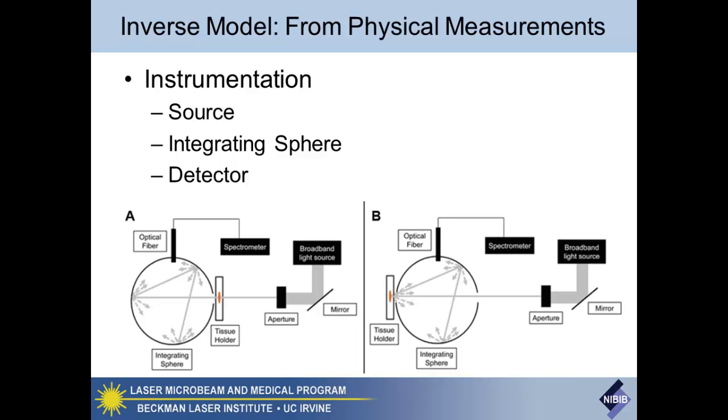There's lots of loss in the system: to have a clean collimated beam and control the beam diameter, you end up rejecting a lot of your source illumination because you have to put in an aperture. With the detector, you can use a multi-mode fiber, anything that will fill the slit of your spectrometer as efficiently as possible. But you're only looking at a small fraction of the total light interacting with the system.